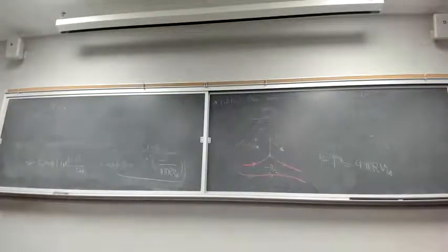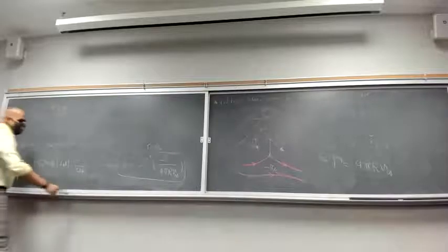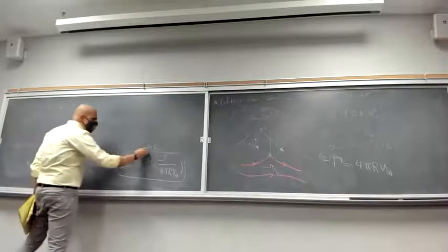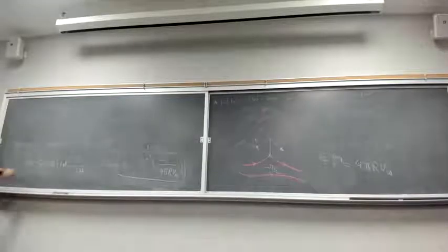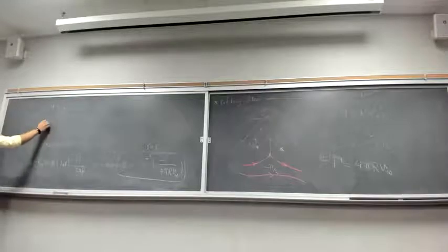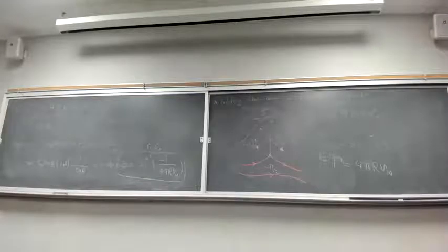This essentially means that, how did we get to this solution? We assumed the stagnation point is on the surface, okay? So if that's the case, then the stagnation point is not on the surface, and r is not going to be equal to R. What does this mean? Going back to your V_r, what was V_r?